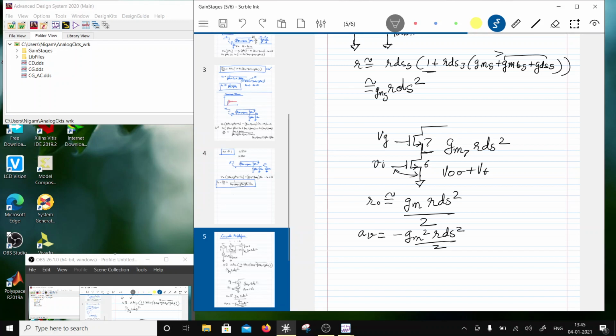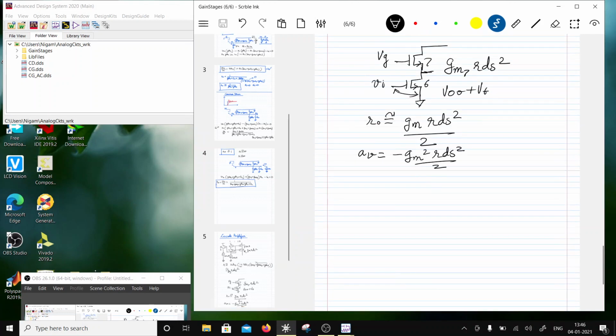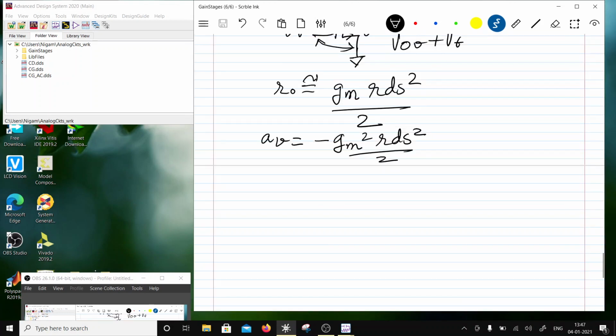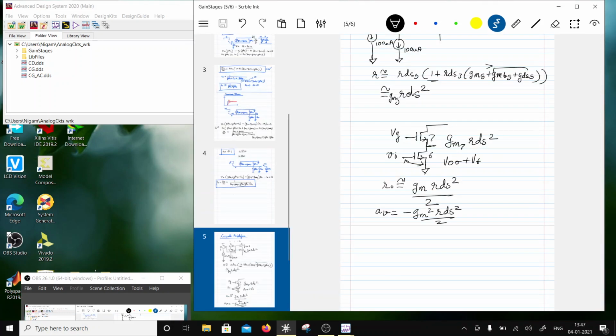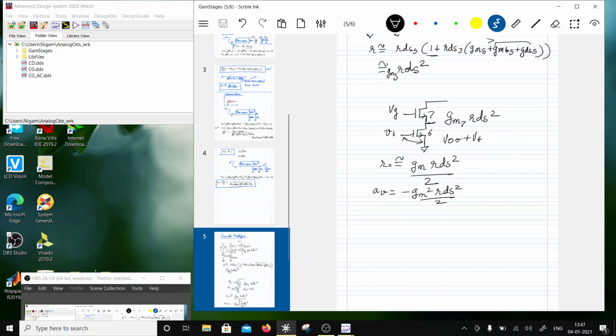So what I want to do is establish here most of the swing we will see. I want to keep it low, so basically this voltage will decide the DC point here in the swing. So let me hold this down to like 0.7 volts, right, or 0.78 volts or something like that, right?